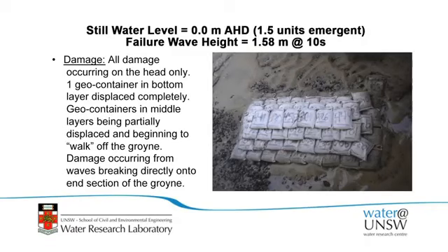We tested it just with monochromatic waves. We basically just kept ramping the wave height up until we failed, or until we damaged it, and then we used what height actually damaged the structure. So we didn't run 1,000 irregular waves and look at what happened. We just kept ramping it up.